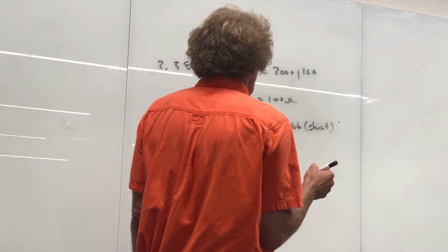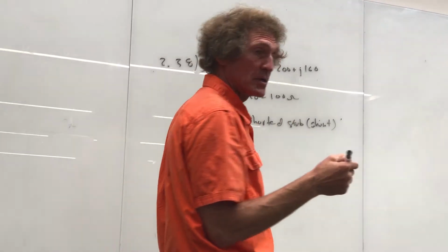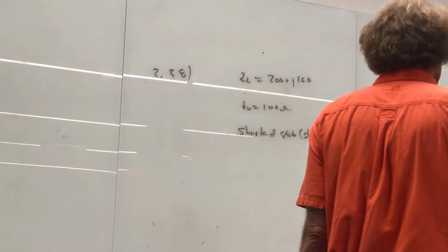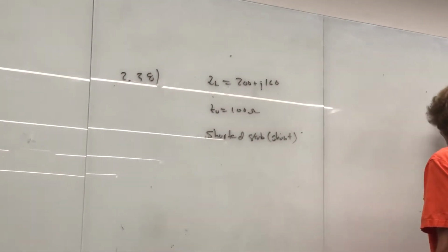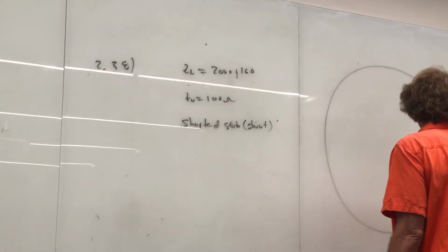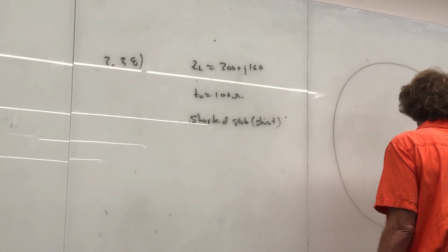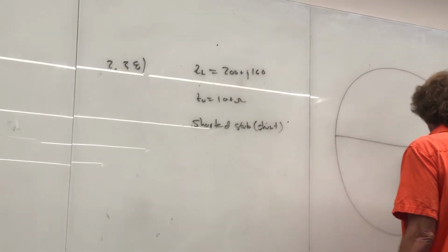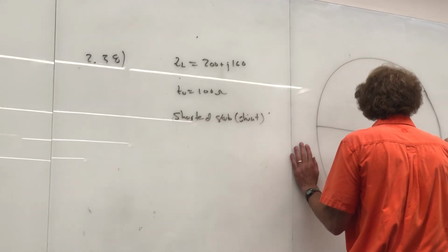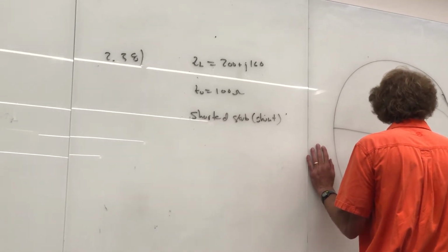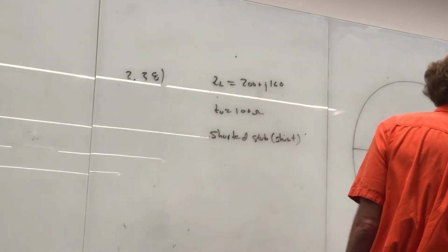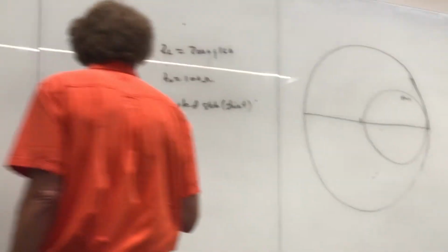Okay. So, y'all have your Smith charts at all? I'm going to just try to sketch the Smith chart. I do this routinely. I'm not saying I'm not good at it, but it's a good place to try to estimate what it looks like. I usually call it the equator, but it's a horizontal line through the center. Then I indicate where the center is, and I draw the 1 circle. This is R equals 1, right there. And now I start doing this problem.